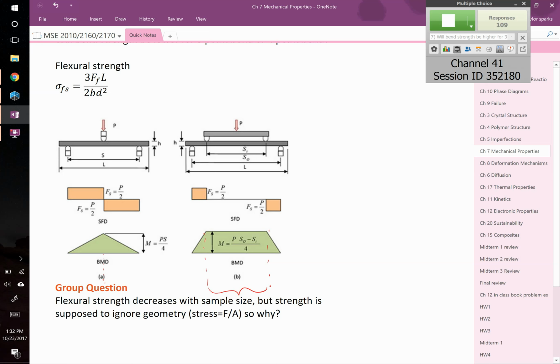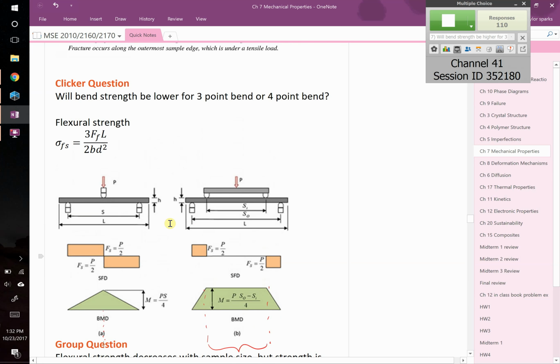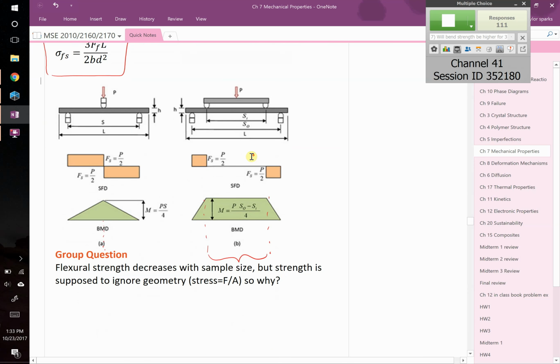Yeah? So is the bend strength the amount of force that it takes to break the sample, or how much the sample can take? So the modulus of rupture, or sometimes the flexural strength, is just calculated like this, right? It takes into account the force, the span, and the sample geometry, B and D, the thickness and the height. And that stress is when your sample breaks, okay? This is commonly used for ceramics because we can't grab onto them like a polymer or a metal very easily, because they would just break. Okay, so that's 3- and 4-point bending.